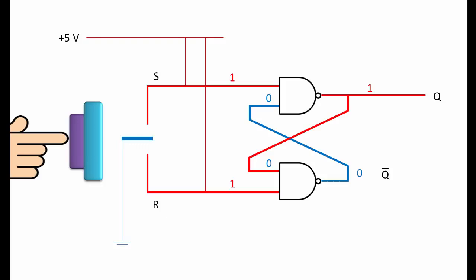On its own, an SR latch has a few uses, mainly in control applications where we need to monitor some condition that might change or change back again and react accordingly. But more importantly, as you'll see later, the simple SR latch is the building block of sophisticated memory circuits.